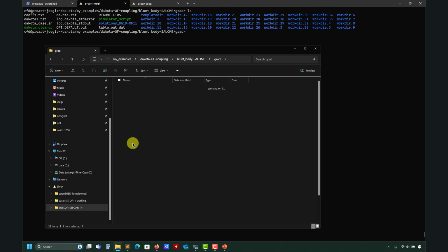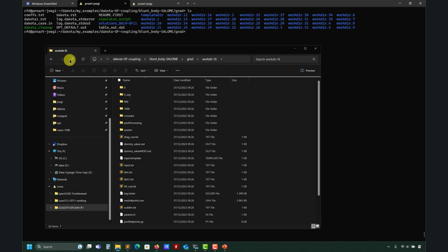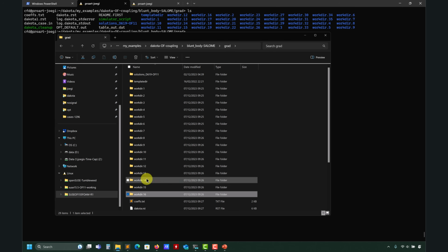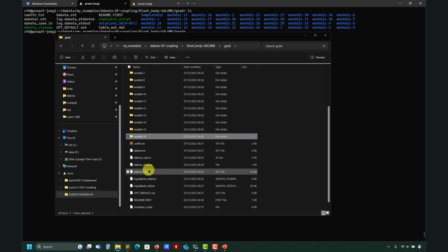You never know, but you also need to check that. For me it's a standard practice, and recommended, to go back one, two, three, four iterations before restarting, because the last record might be corrupted depending on the concurrency that you were using. So this is it. And now how do we start?